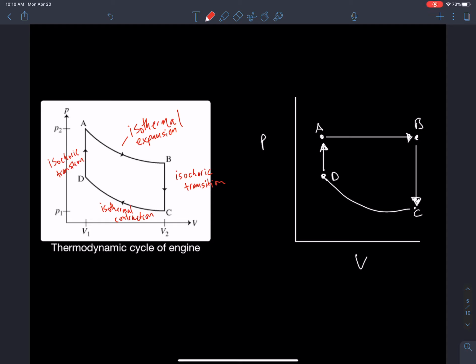So within that graph, we have 4 different transitions. And in each of those transitions, we should be able to calculate either the work being done or the work done on the system, okay? And if you subtract the two, you would find the total area within that curve, which is the actual useful work being done by the piston, okay? So the total work being done minus the work being done to reset the system would give me the useful work being done by the system.